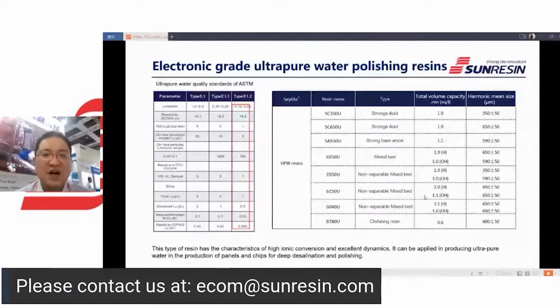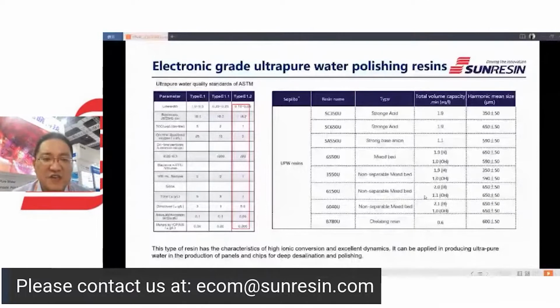After our tests on all the key parameters of the outlet water, such as resistivity, TOC, online dissolved silica, oxygen, and even particles, the water fully meets the electronic grade UPW requirements.